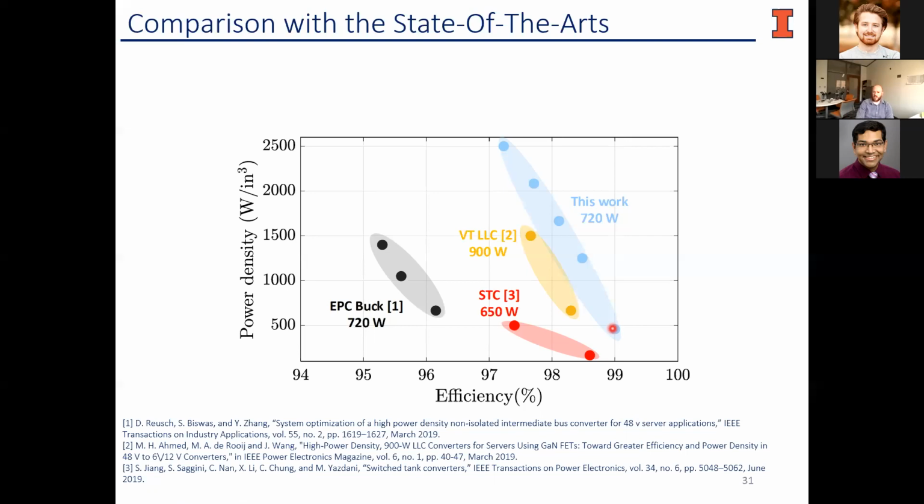So for the most part, this is, I would say, a pretty good apples to apples comparison, right? These are all converters that are academic converters. So all of them kind of draw a box around their converter and say, this is my power stage. I don't think any of them are necessarily including their controller in their power density, and may or may not be including their auxiliary power, certainly not in terms of their volume. They should be including that in terms of their efficiency. And all of them don't necessarily report their EMI results on how effective they are at passing those standards.